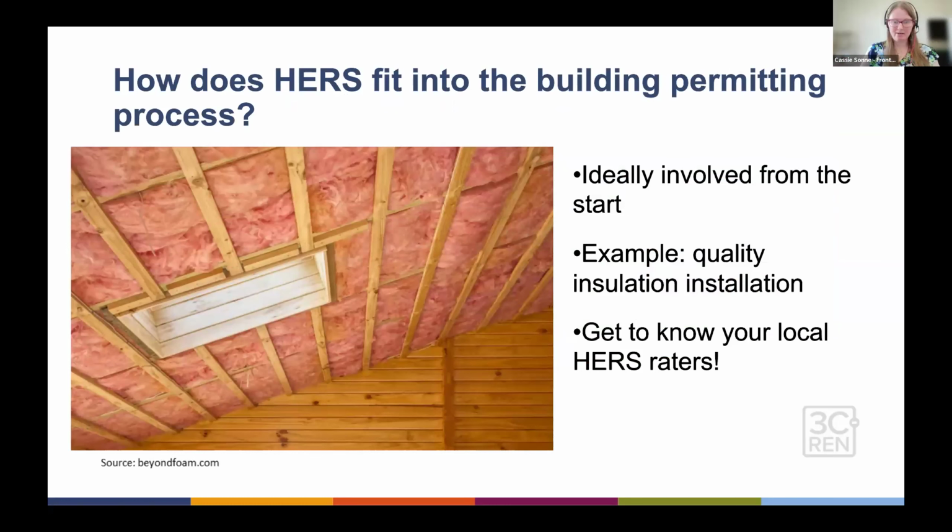So now that we know a bit about the history of HERS and what HERS testers do, how does this all fit into the building permitting process? Well, I would argue that the best time to get a HERS rater going in the project is at the beginning. And this is so they can inform the contractor about when they need to perform inspections and testing. And that kind of coordination can matter a lot more than might be apparent at first glance. So for example, quality insulation installation has the highest failure rate of all HERS measures. And if that insulation gets covered up before the HERS rater inspects it, that results in an automatic failure.